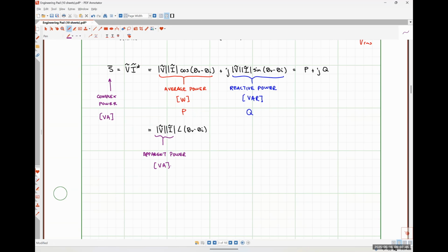So effectively, it's telling you that not only can it handle resistive loads, but it can also handle smaller inductive or capacitive loads as well, like a fan or something like that, okay? So we use apparent power to design to because it's kind of like a worst case scenario, okay? What I mean by that specifically is we're taking only the magnitude of our voltage and the magnitude of our current and we're multiplying them together.